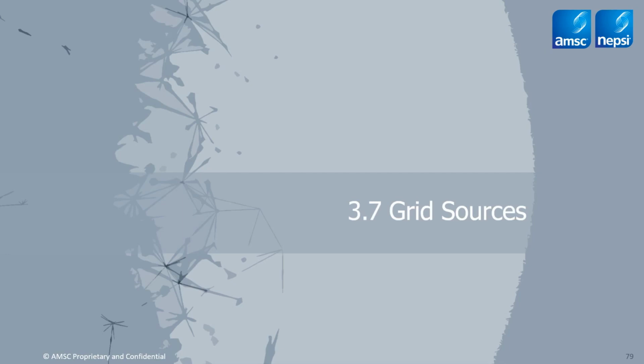Interestingly, for those of you who have some familiarity with saturable core reactors, that's a whole different beast that we have to consider if it happens to be available in a circuit that we're modeling. So if you are including something with a saturable core, you may want to transition to a different form of analysis than an AC network analysis, especially if it's key and critical and important that the change in inductance is simulated.